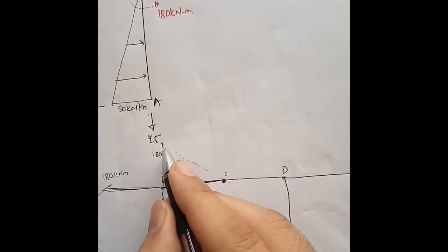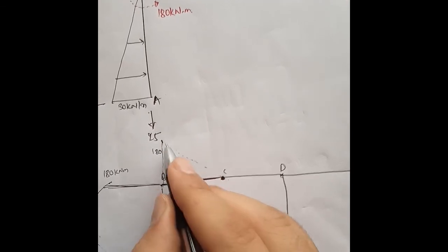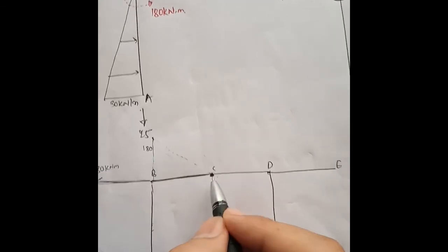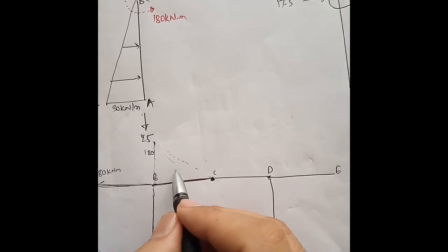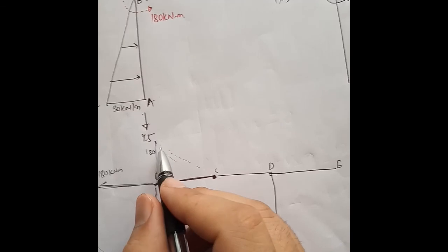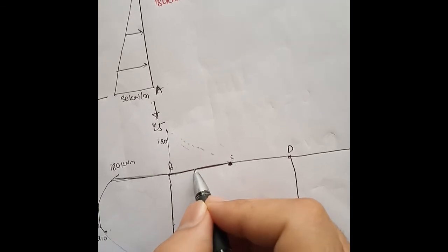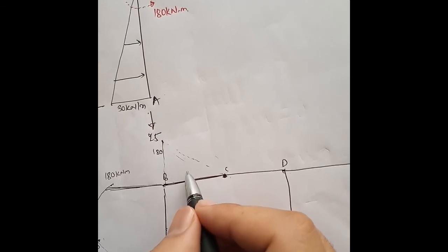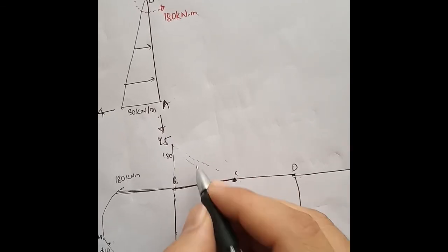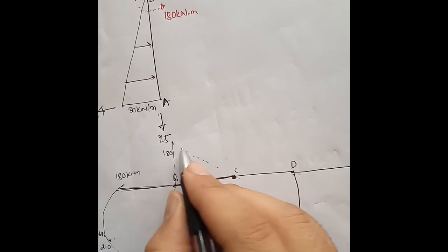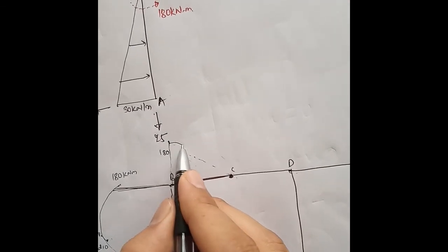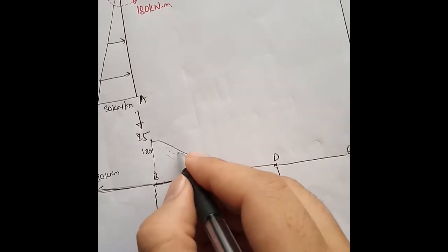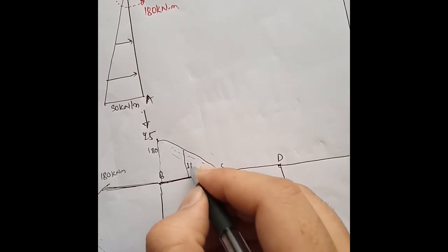The parabola can only be assessed by the midpoint. So 180 plus 0 by 2, 90, so you have 90 at the midpoint here. Likewise we have already determined that in section BC the mid moment is 110, so 110 lies above this 90, and the curve must pass this way. So this is the curve of this section, where at the midpoint there is 110 bending moment.